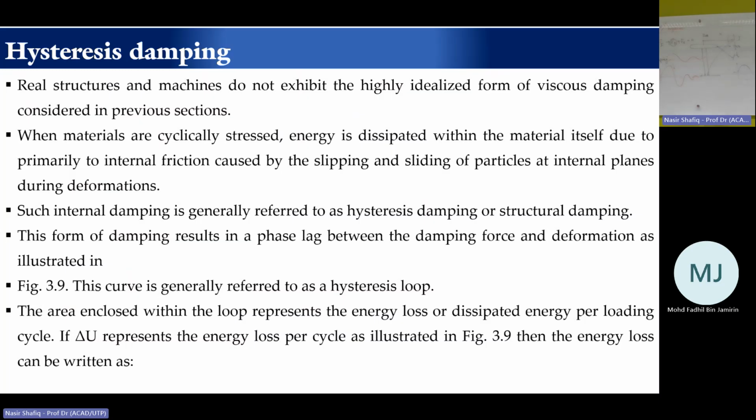So when material is cyclically stressed, energy is dissipated within the material itself, primarily due to internal friction caused by slipping and sliding of particles at internal planes during deformation. Right?